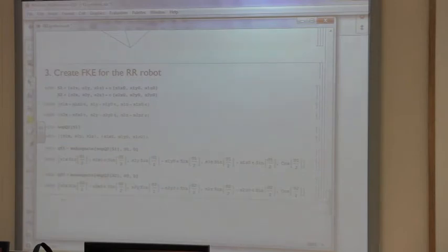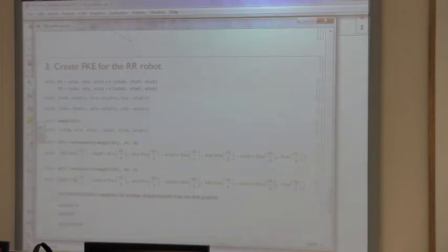Okay, so I want to put some text. Okay, here. Forward kinematics equations for relative displacements from the first position we have defined. Okay. So we just multiply those two, right? Quad mult QS1, QS2. And this is the forward kinematics equation. So forward kinematics equations equal to that.